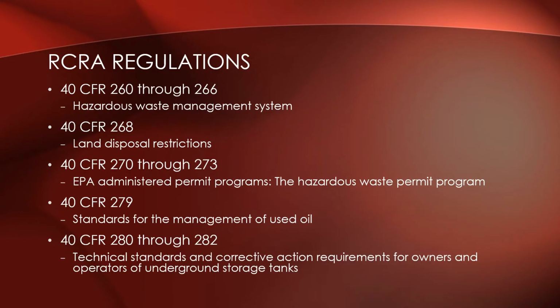The RCRA regulations that must be complied with for most explosive hazardous waste generators and TSDFs are 40 CFR 260 through 266, 268, 270 through 273, 279, and 280 through 282. 260 through 266 outlines a hazardous waste management system. 268 overviews land disposal restrictions. 270 through 273 overview the hazardous waste permit program.